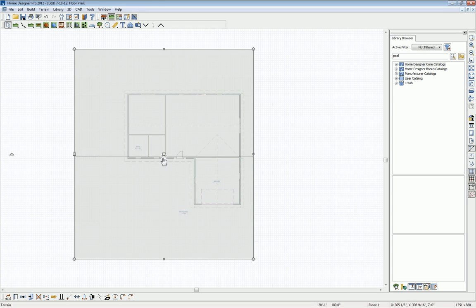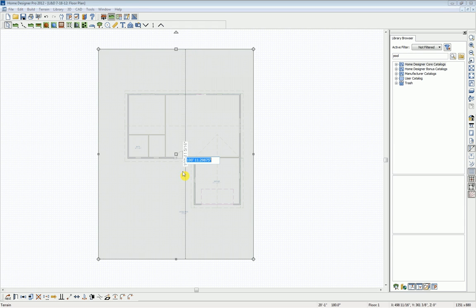Right now it's 89 feet. I'm going to single click on that temporary dimension that's perpendicular to the edge I selected, and I'm going to type in 77 feet. Our programs think in inches, so if you're not wanting to do inches, make sure you put that foot marker in there. And I'm just going to hit Enter on my keyboard. So that will modify to the correct dimension. I'm going to do that lengthwise here. We're going to single click on that temporary dimension again. Let's do 135 feet. Hit Enter.